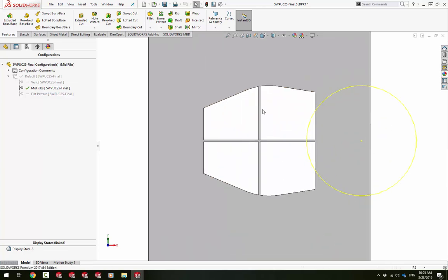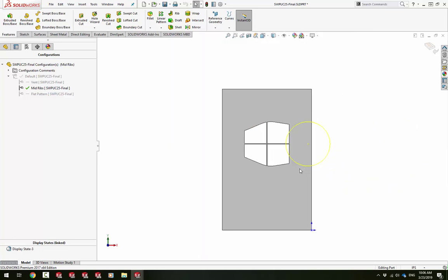I expect that the two ribs will go exactly through the middle of each direction. So they would be equal: this one is 31.309, the other one is 31.309. Obviously here it's kind of harder to measure. I need to find the middle of them and the intersection with the original cutout, but they should always be equal.